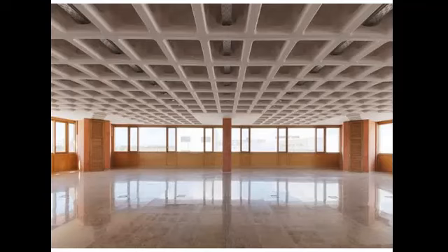If you look at the surface, you can see it is wide. Look at it from the floor here to here. If it is a solid slab, you can't manage not to have another column at the center here. At least one column at the center if it is a solid slab. But because it is a waffle slab, there is no column here, and it is, of course, efficient. So that's why you should use a waffle slab.